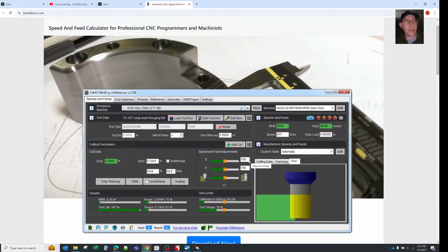As you guys know, every time you clamp on something, you're putting stress into the part, right? And you guys are machinists. You know that when you remove that material, the stress of the cut itself has to go somewhere. Now, if you're doing a real good job and managing that with high-speed machining, maybe dynamic toolpaths in Mastercam, a lot of times you can work without putting too much residual stress into the part. But if you're clamping on that thing and machining it, what's going to happen as soon as you release those clamps? Out of tolerance, right?